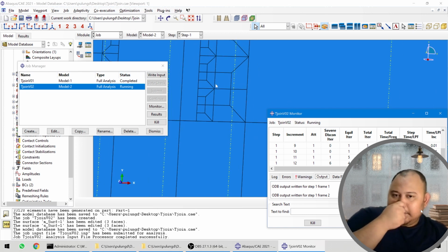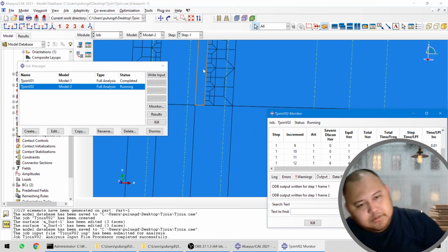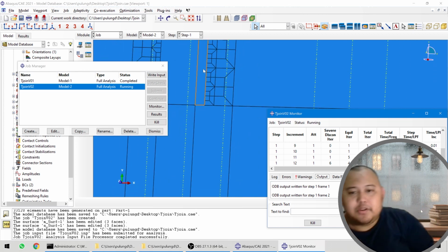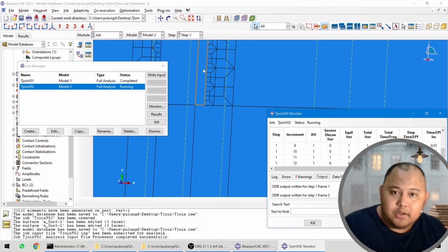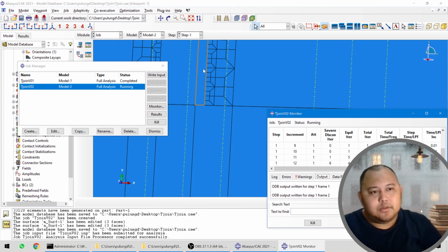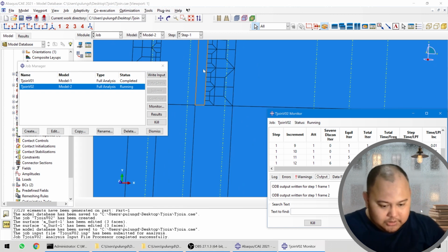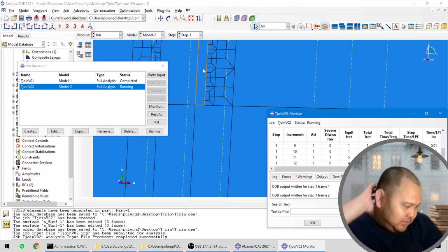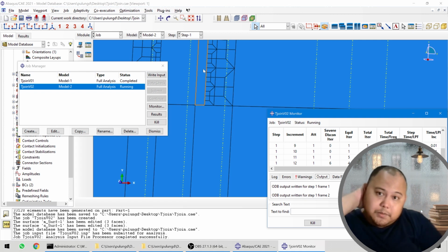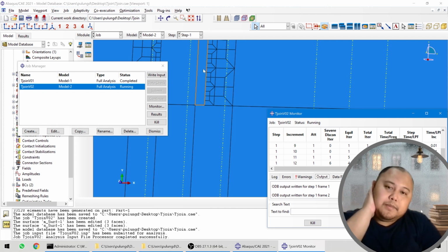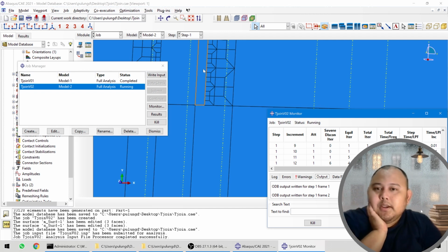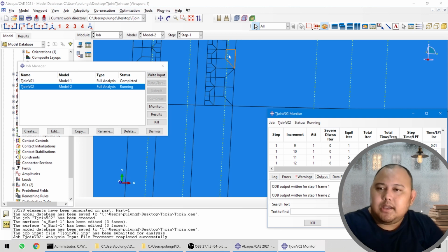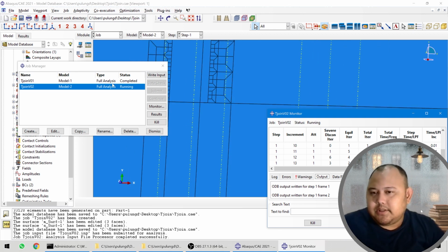And it's really nice if you have a mesh like that, especially if you have a contact problem and you want to make sure that you have this nice transition. It can be easily done in software like HyperMesh because it's a special purpose meshing software. But in Abaqus, the CAE is not really robust in doing that kind of stuff, right?